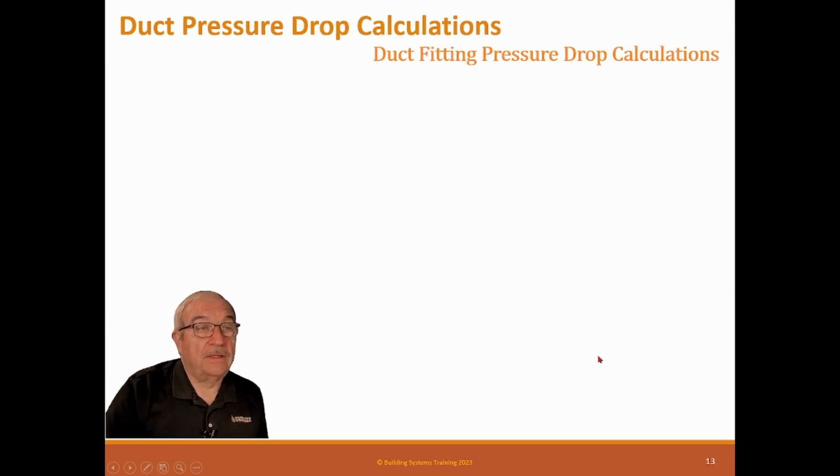Okay, now duct pressure drop calculations. When an engineer designs a job, he'll lay out a duct system for the job, and he'll lay out all the grilles and registers and all the airflows. And then he has to calculate how much pressure the fan needs to push that much air through that ductwork. To do that, he has to do a pressure drop calculation. And nowadays, it's easy. They just have a computer program, stick the ductwork in there, and it figures that all out for them. But here's how you do it manually.